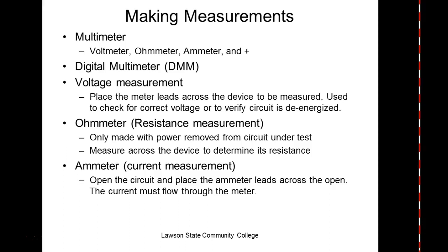So which ones do you think we use most often? Volts and ohms. Because ammeters, you have to do what? You have to break the circuit to put the meter in there. Because to measure flow, you've got to put the flow into the meter.